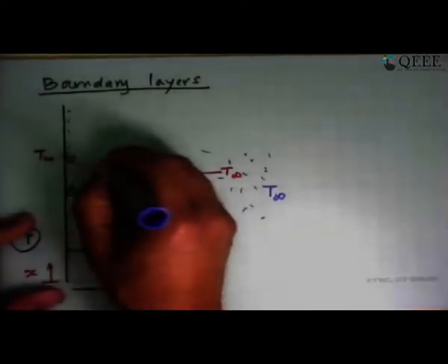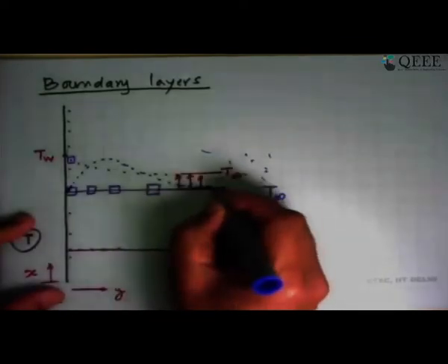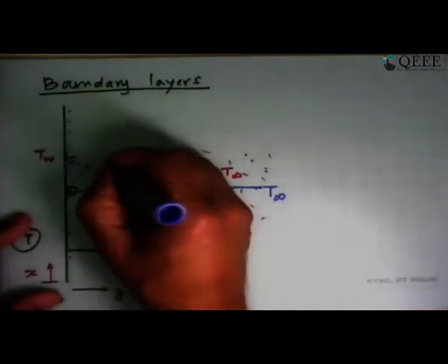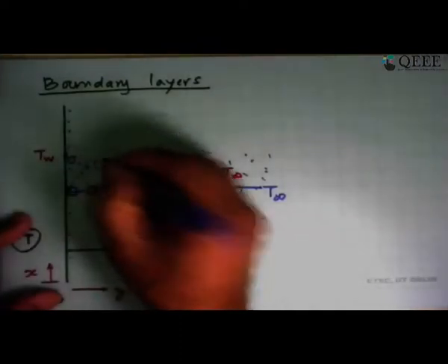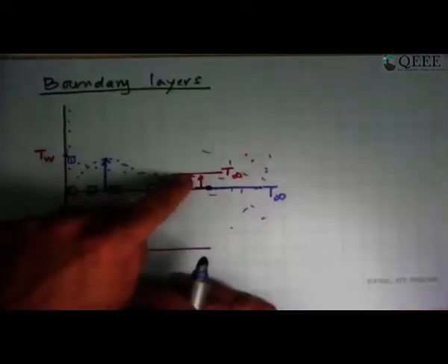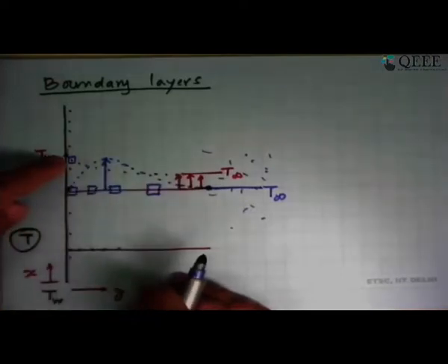So the only way this can be satisfied is that you end up getting a boundary layer where the velocity profile is like that, and finally it becomes zero outside. So there is a point in that boundary layer where the velocity is maximum. The temperature profile has a steady decrease of temperature from the surface outwards, with a surface plate temperature of Tw.